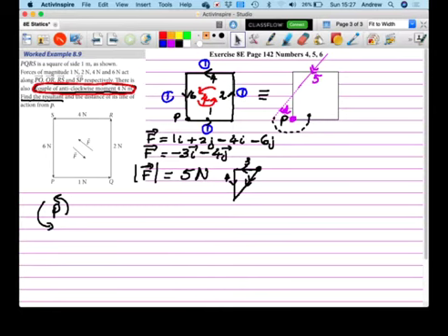So that's in the positive direction. So, whoops, I didn't mean to do that. Put that back. So we've got to have 5D. So it's going to be 5 lots of D is equal to. So we're now taking moments about P for these forces. Well, for that one, it's just going to be 1 times 0. And for this one, because it goes through P, it's going to be 6 times 0.